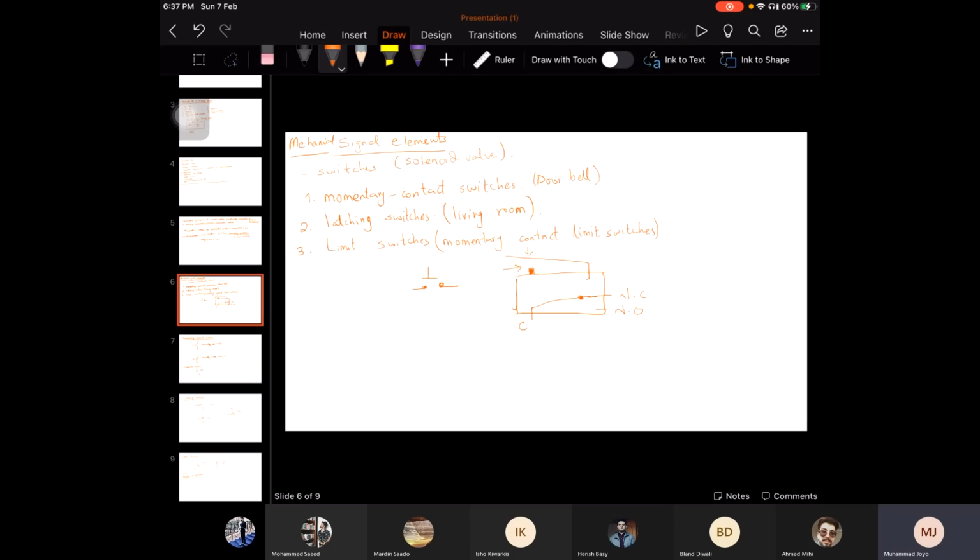Let's say that a relay can be used in an environment where a maximum current of 20 amperes or 10 amperes is required. Usually it is 10, or maximum it can be 20. But talking about contactors, they can bear up to 32 to 50 amperes. They can go more as well, depending on the size. Okay, and the functionality of both relays and contactors is the same.